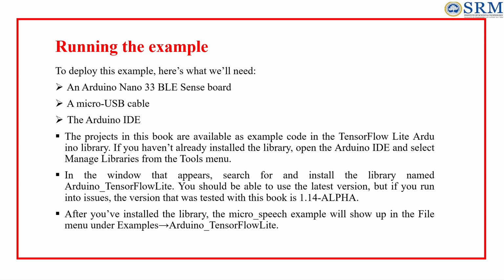If you have not already installed the library, open the Arduino IDE and select Manage Libraries from the Tools menu. In the window that appears, search for and install the library named Arduino TensorFlow Lite. You should be able to use the latest version. But if you run into issues, the version tested with this book was 1.14 alpha.